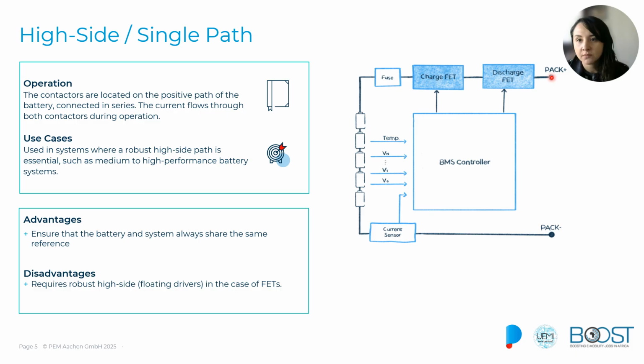These setups ensure there is better management of the power path, because we ensure that the ground is always connected to our systems, and because of that we minimize the risk of accidental faults from losing that reference. It also has a clear and effective separation of the battery from the systems during any fault condition and when any of these contactors are open.